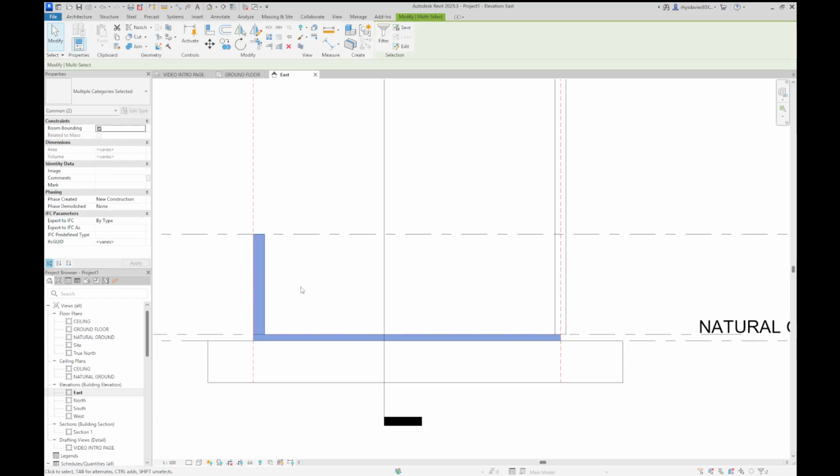This wall here was built using a height constraint or a level constraint, and it was done using the finish face exterior, and that means the wall has been built exactly where I want it, which is right up to the slab edge. That is the result that I want for this particular project.